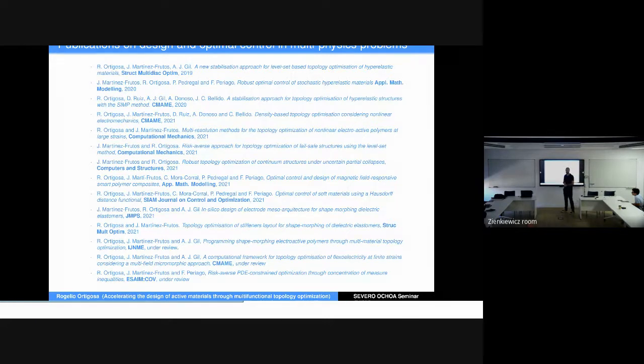I've seen that in the context of mechanics in a dynamic problem. I was testing the Saint Venant material and I said, why can't I use the Saint Venant material? I'm not showing this here today. I have it in a different presentation. It was in the context of the twisting of a column. I've tried the twisting column with Javier many times in the context of fast dynamics. But I know that in the twisting of the column, at the bottom, there are going to be tractions and compressions. And the Saint Venant suffers a lot in the compression. It loses ellipticity in the compression region.